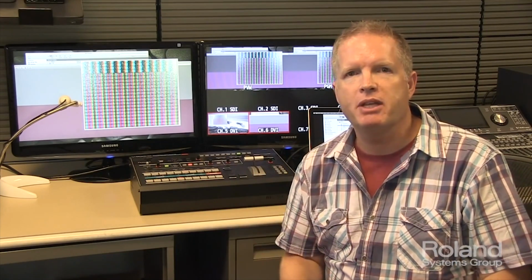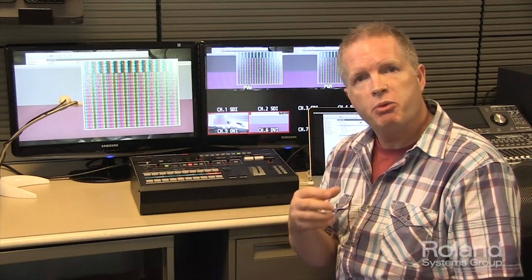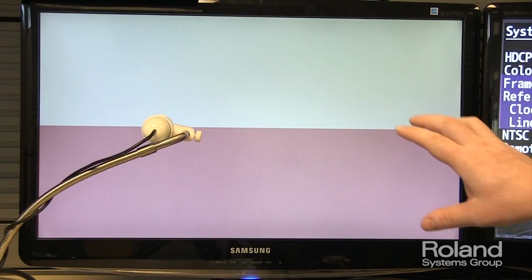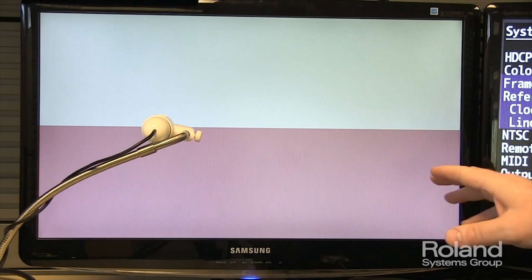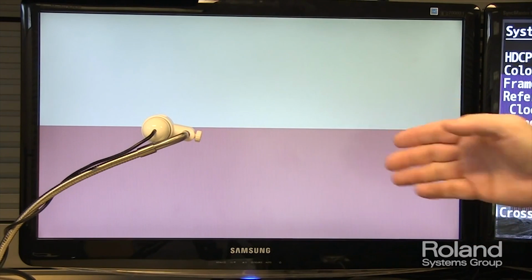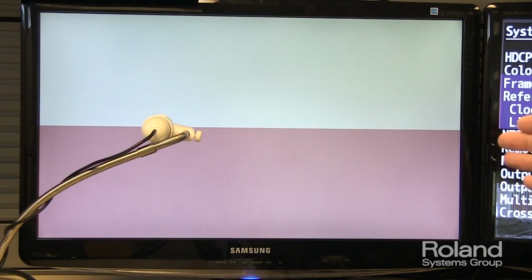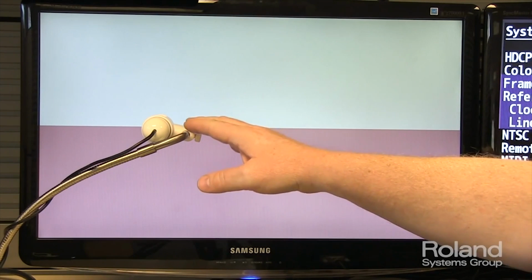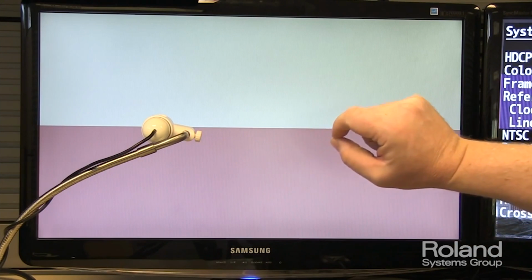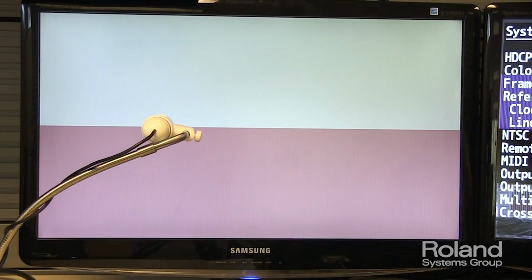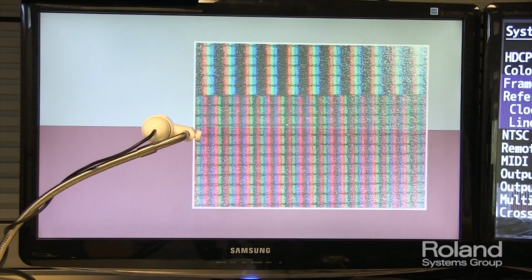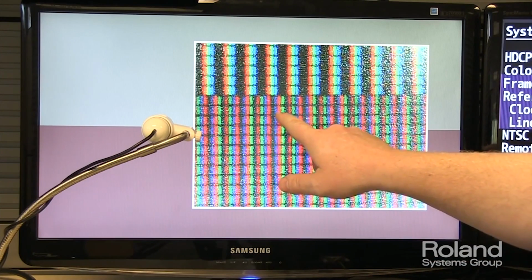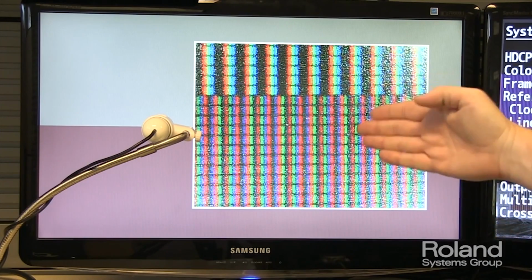Instead of showing charts and diagrams, let's take a look at a test pattern as well as a real-life example from a spreadsheet. The first pattern we have here is a 1920 by 1080 image with red, green, blue lines in sequence that is very hard for chroma sampling to sort out. We've connected a little USB digital microscope that's looking at the pixels at about 200 to 300 times magnified, and we're running that through the switcher and have put it into a picture-in-picture. So you can see roughly here we've got the red, green, blue nicely organized into lines.